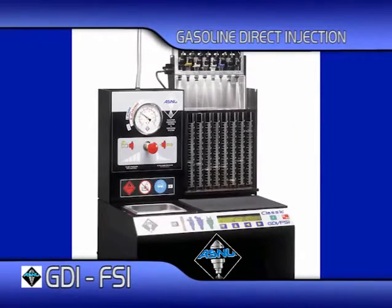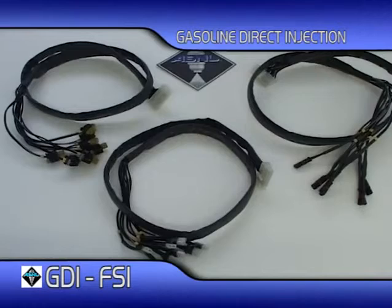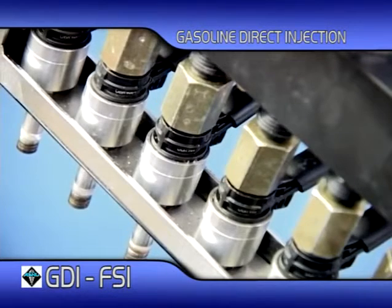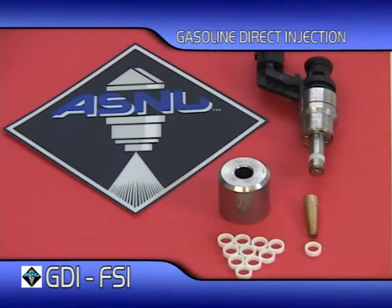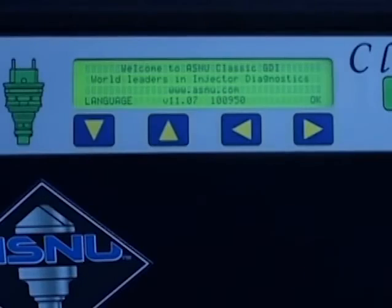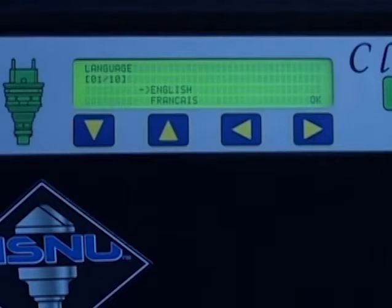The ASNU Classic GDI machine shown here and the ASNU GDI adapter box are designed to test and service any GDI injector currently in service. There are a selection of wiring harnesses and fuel rail connectors to adapt the system to any GDI injector. The system comes with a service kit to replace the Teflon head seals that require renewal before the injector is refitted to the engine. When the ASNU Classic GDI machine is switched on, you will see this welcome screen display.